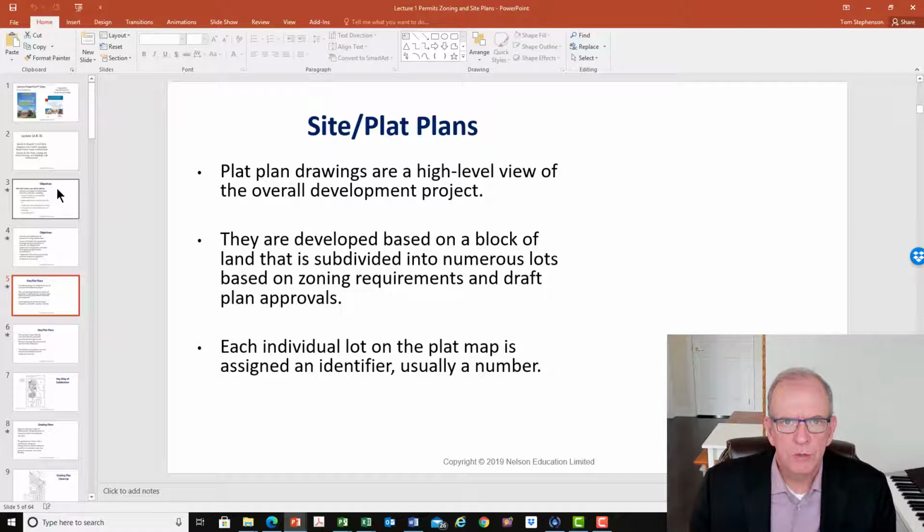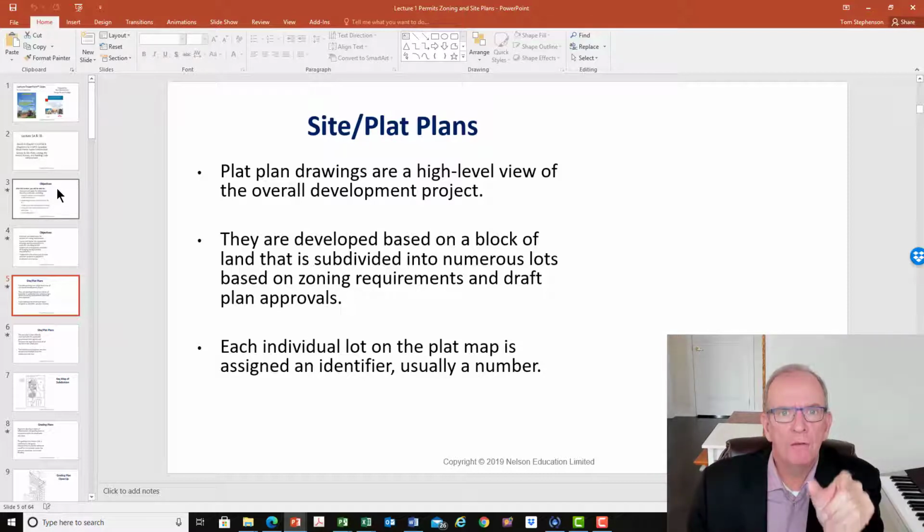So that's a good resource for that, because again, there will likely be a few questions that would come out of the pool on that. So you want to at least know how to calculate a ridge board and what the ridge board deductions are. Like, how to calculate a common rafter point length. If I've got a 1.5 inch ridge board, how much would I deduct from that? Half the thickness of the ridge I would deduct back.